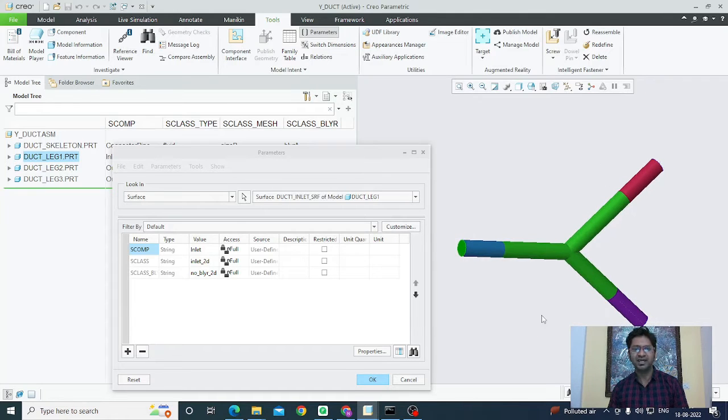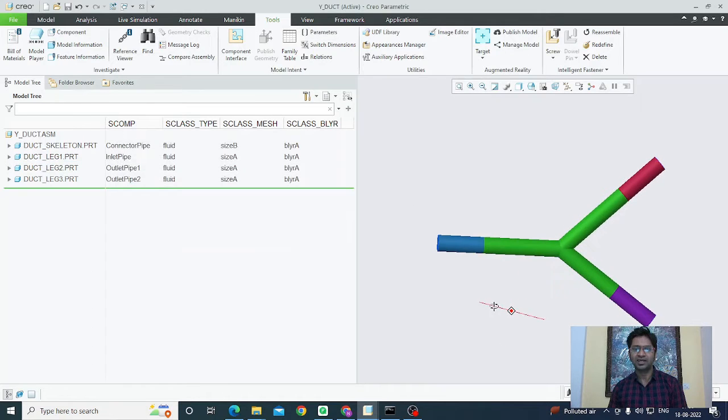So we will be using the relation between this 2D class and the 3D class, and we will specify that we don't want boundary layers to be created near these locations. So this is all about the CAD modeling point of view. You can add a specific class on the parts where you want boundary layers to be created.